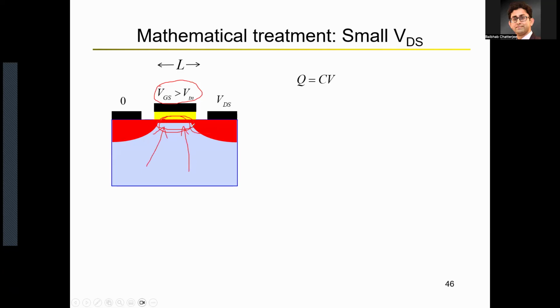You also draw a few electrons from the source and drain regions. So you get excess of electrons just below the source. And excess of electrons is basically saying that you have effectively an n-type region, because n-type regions have excess of electrons. P-type regions have excess of holes. Okay. So to form a channel, you need to apply a positive gate voltage if this is an NMOS.